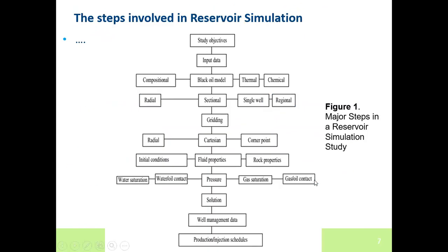So Figure 1 here gives an overview of major steps involved in a reservoir simulation study, starting with setting the study objectives down to setting out production and injection schedules. And if we go through it, even though this is not comprehensive, after your study objectives have been set, you need to compile your input data, of course, from different sources.